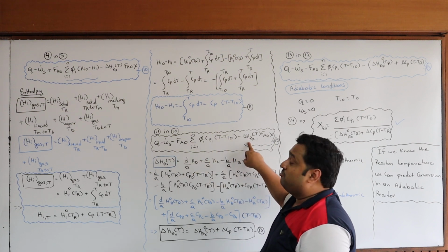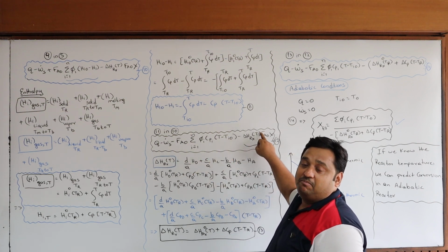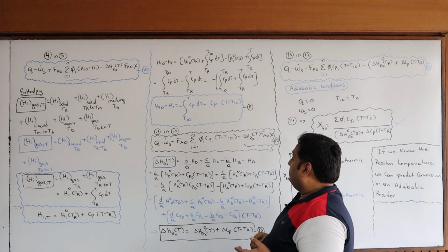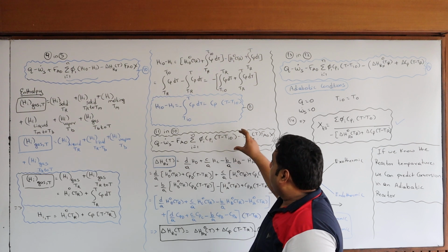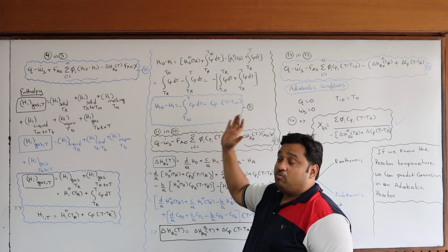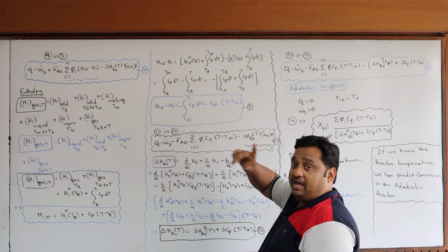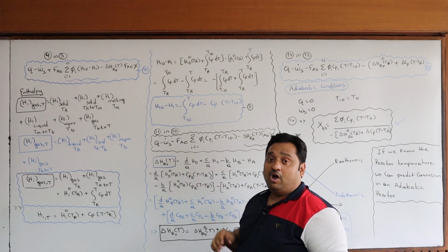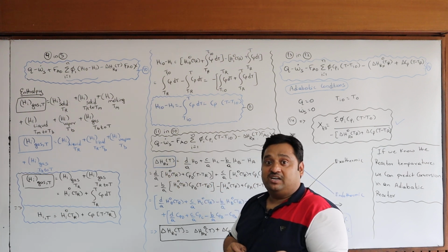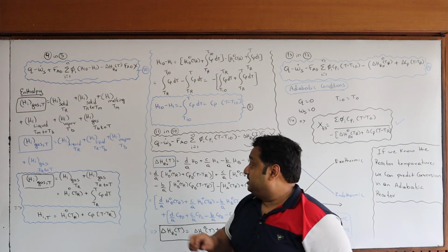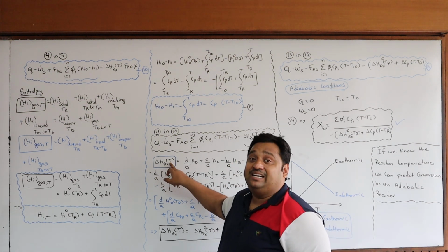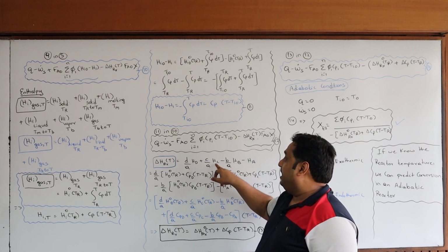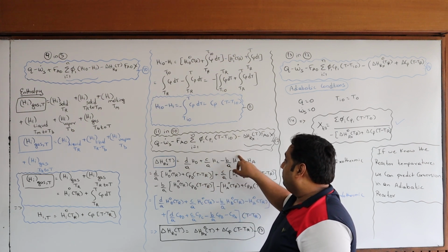Now, let us take what is the enthalpy of the reaction at temperature T. Okay, let us evaluate this parameter, because finally we have to take the temperature term on one side and conversion on the other side. What is the heat of reaction at reactor temperature? That is delta H of reaction at T, which is d by A into Hd plus C by A into Hc minus B by A into Hb minus Ha.